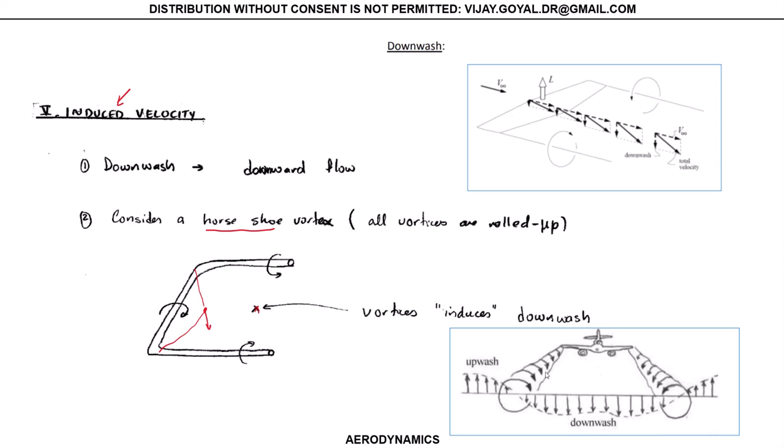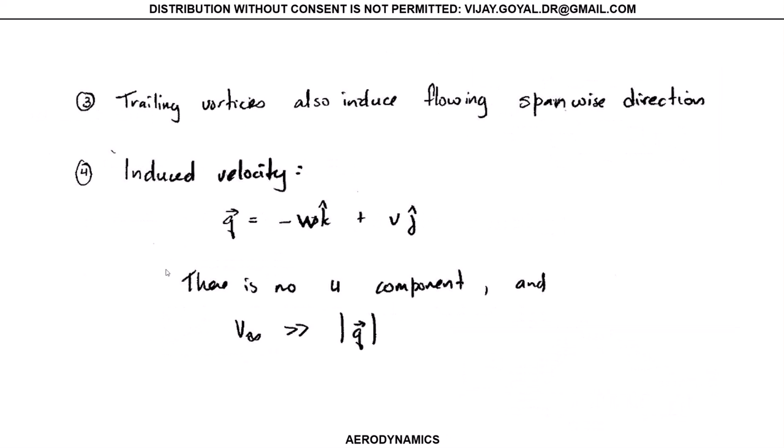So this is kind of what it's really going to look like, and this profile is going to change as I move away from the aircraft, and that actually pushes the aircraft down, which you cannot avoid. You want to try to minimize it, but you're always going to have this because you have lift. Okay, because you have circulation, you will have this. It's impossible to eliminate.